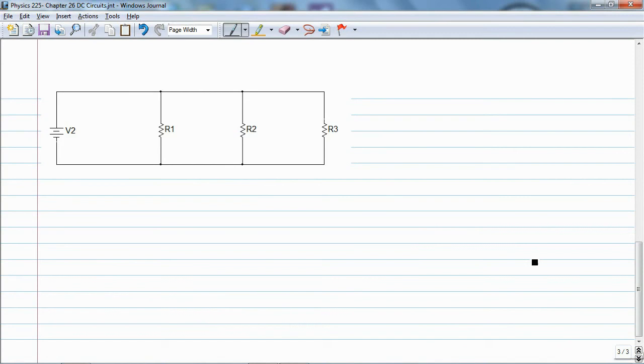And for our last relationship, we have a parallel circuit, and I know that this actually I wanted to be T, forgot to change that. I know that the current, I wanted to go for current here. The current through Rn, whichever resistor I want, is equal to Vt over Rn. But Vt is just equal to I times RT, and I'll divide that by Rn, and now I get the current through the specific resistor that I want based on its configuration.